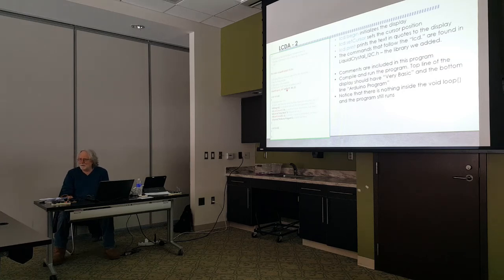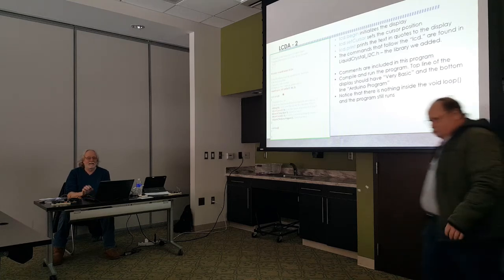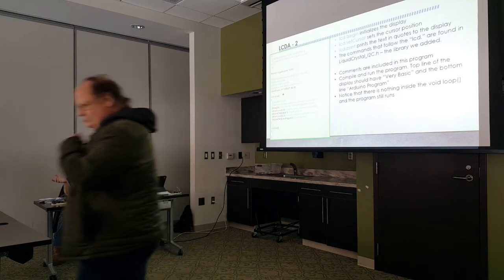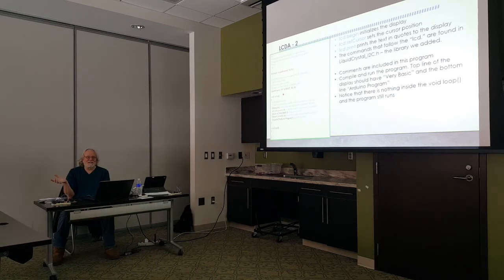Bill Hopkins was having trouble getting his display to work. And it turns out his display, although it came from the same company as mine, had an address of 3F. Do any devices have duplicate addresses? Yep, different manufacturers. There's only 256 addresses. There's lots of devices out there in the world, so yes, it's very possible.